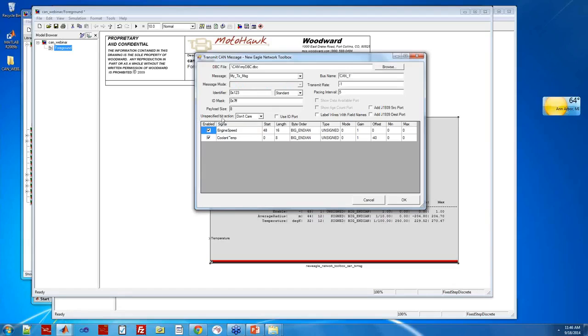You can specify, in our message it's not completely filled, so there's some open bytes. We can specify how to fill those bits, set them to 0 or set them to 1. Certain protocols such as J1939 specify that you must fill unused bytes in a certain way.